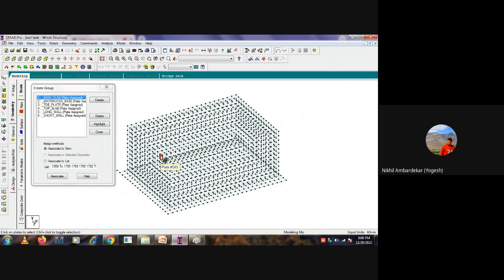When we create the different small segments or generate the plate mesh, why do we stick with those numbers? Whenever we create different small segments of that 12.5 meter wall, we always put 25. When we go with 8.5, we always provide 17. If those numbers are not matching, what happens?